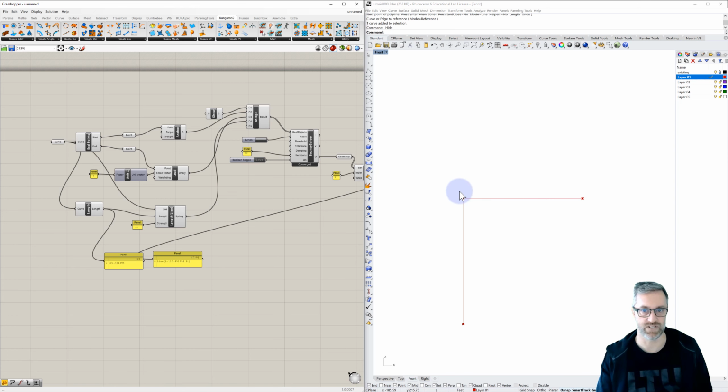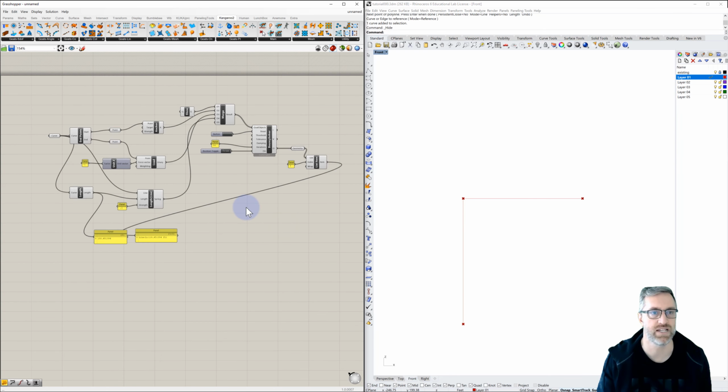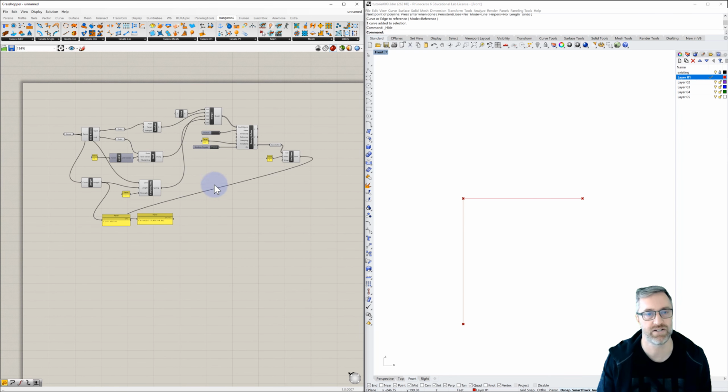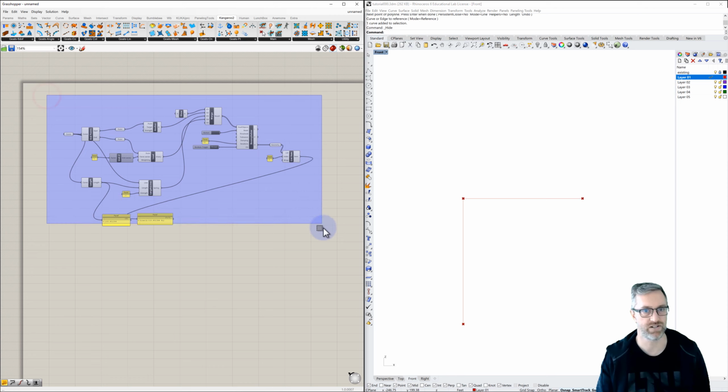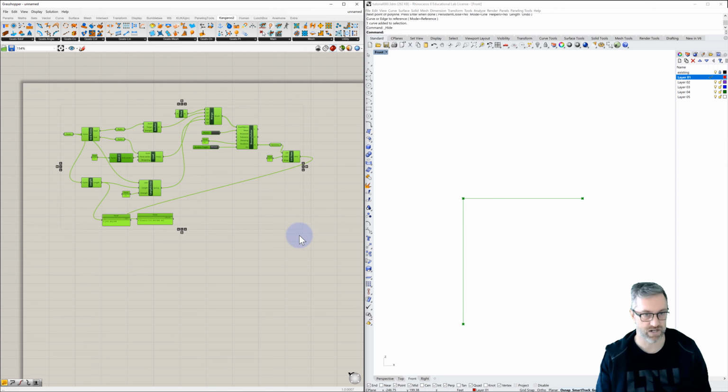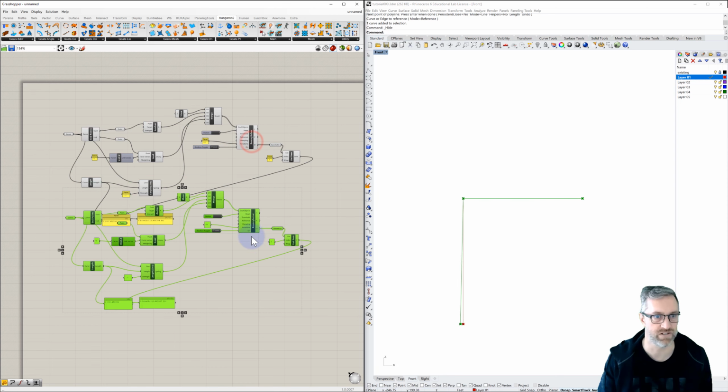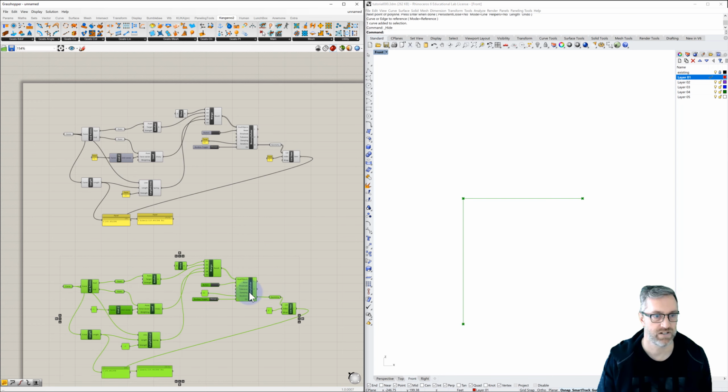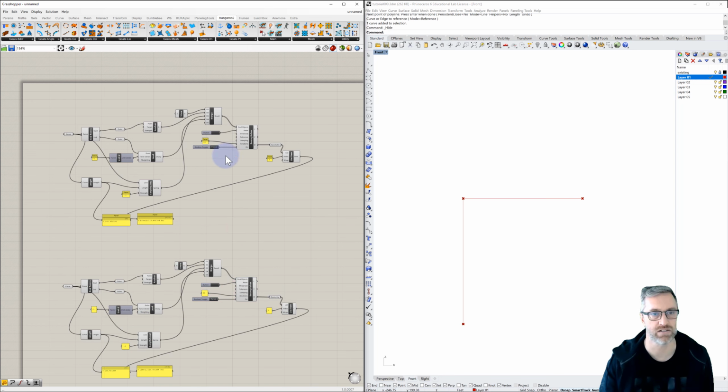Because what we've done is we've simply locked one point in its location. We've applied a force to a second point, and we can see where it resolves and how it plays out. And we're allowing the simulation to stretch this line. So that's really, really simple. Let's copy all of this, and we'll make a couple changes, because what I want to do is create a really simple two-dimensional catenary hanging chain model like we saw with Gaudi.